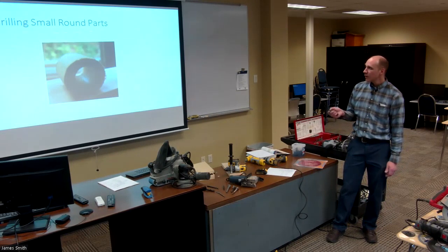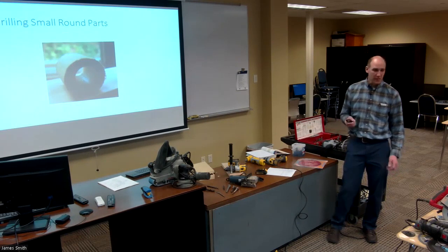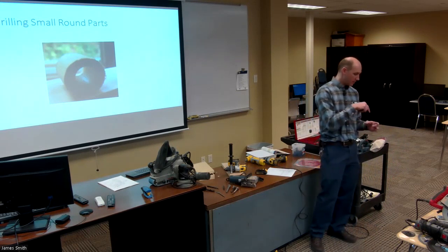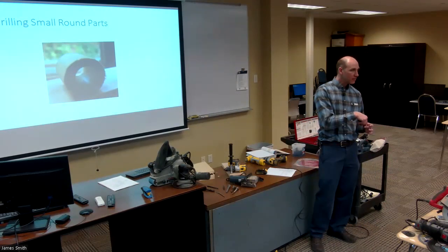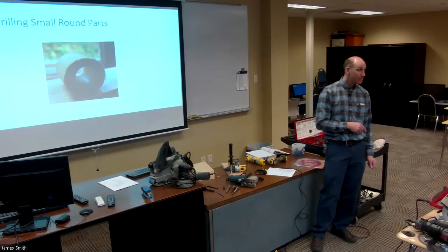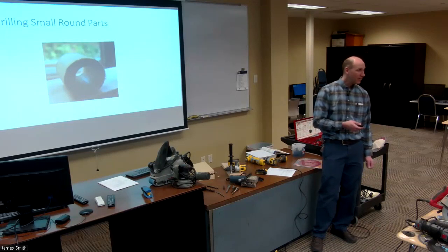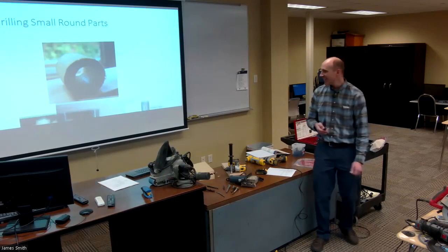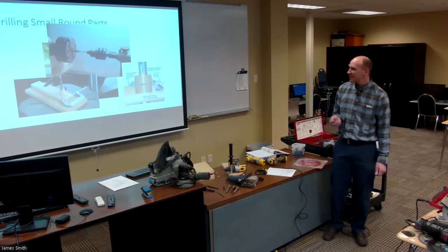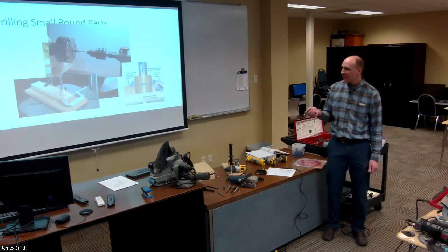What about drilling small round parts? In this one in particular, we have to drill a center. I had to do this one time. I was making a toy truck, and I had four little wheels, and I needed the axle holes drilled perfectly in the center. How would you drill that? Andy, I think you probably know. Use the lathe. Yeah, that's what I would do. That would be the best option, right? Just chuck that thing up and use your drill. But you can get creative.